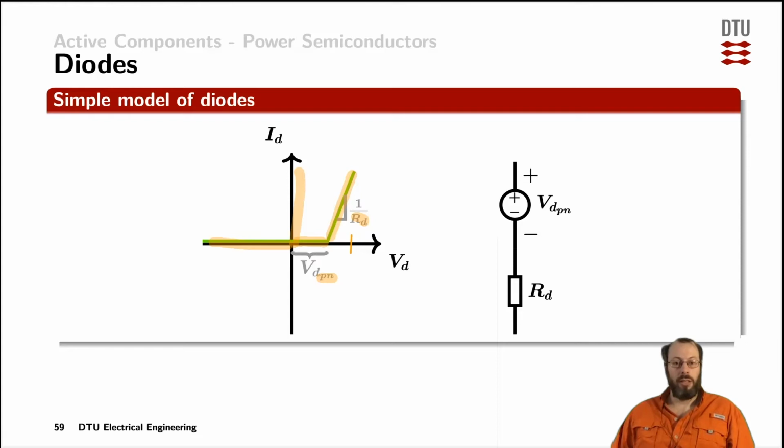So when conducting a current through a power diode, we actually get a voltage drop across the static PN junction, which we can model through a DC voltage source. And we have that extra voltage drop at the operating point across the resistances leading to the PN junction, which can be modeled by an extra resistor in series with that DC voltage source.